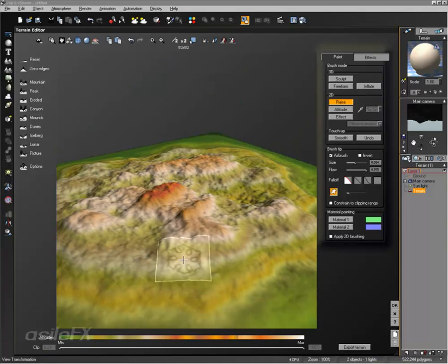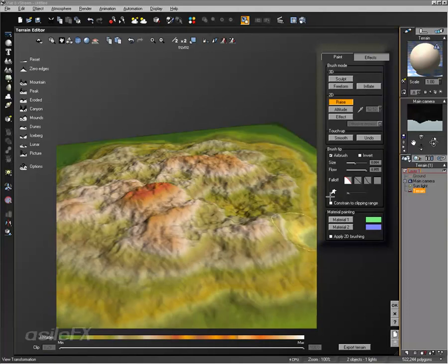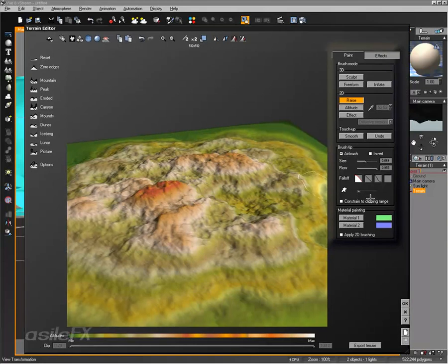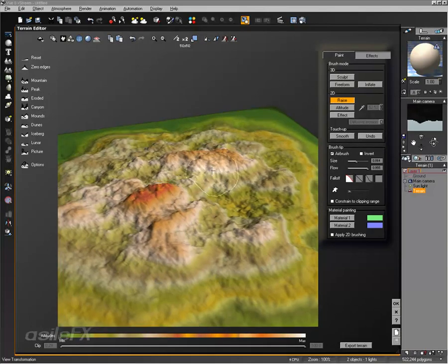The brushes used for painting are inverted of height maps. So instead of black being the lowest part of the brush, it's actually going to be the highest. So in this case, it would need to be reset and inverted. You can right click to turn it off, and the slider that's right next to it will allow you to adjust the resolution and the polygon count based on the brush effect. It will increase the resolution of the terrain and polygon count in order to conform a little better to the brush.